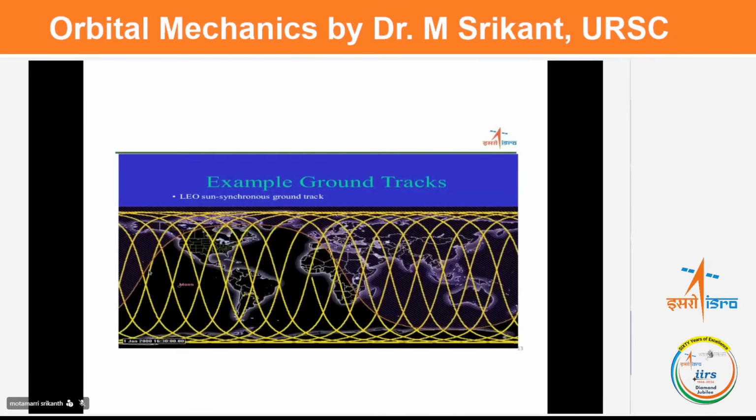Assume that you want to cover only plus minus 22 degrees of the tropics. Now I have taken plus minus 82, but you can take this yellow color band, which shrinks to plus minus 22 degrees. If I want to cover the tropics within a certain number of days, the revisit time was roughly 7 days. So a single satellite is giving 7 days.